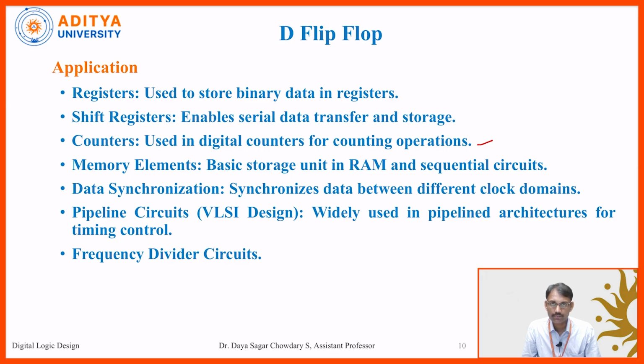And memory elements, because it naturally stores the data, that is why it is used in memory elements like RAMs and sequential circuits. And data synchronization, which synchronizes data between different clock domains. And pipeline circuits, which we mostly use in VLSI designs. They are widely used in pipelined architectures for timing control. So in order to maintain our timings and reduce time delays, most of the time we use these flip-flops.